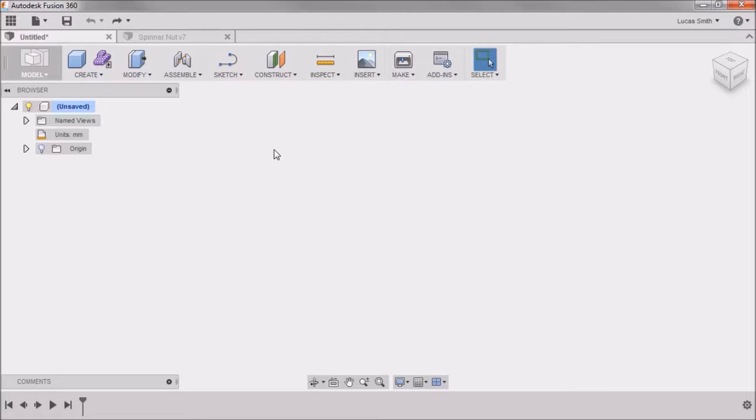In order to start a sketch on a face, there must already be existing 3D geometry, which I will demonstrate a bit later in this lesson. However, I'm currently working from a blank document, so I'll select one of the 3 origin planes to create my sketch. One way of beginning a new sketch in a blank document is by selecting the Create Sketch tool.